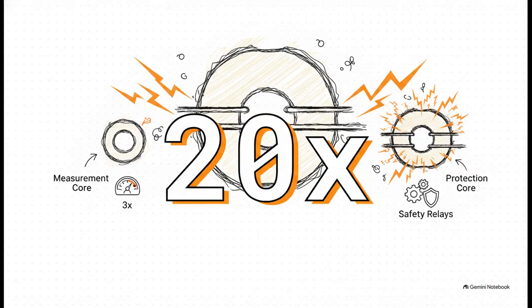But think about what happens during a severe grid fault. The current surging through that primary wire can easily spike to 10 or even 20 times the normal limit. Boom! It's a catastrophic event. And while the measurement core is safely tapped out back at 3 times the normal current, that protection core is now facing a massive 20x surge that it absolutely must accurately capture and report to the safety relays.